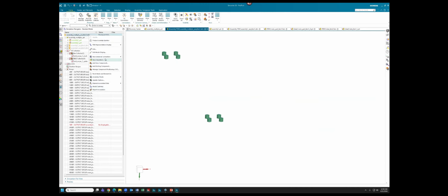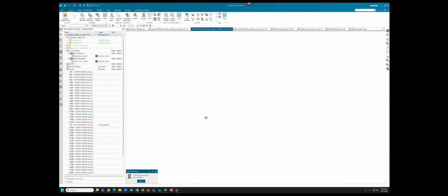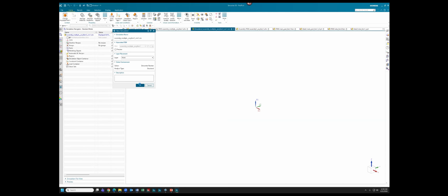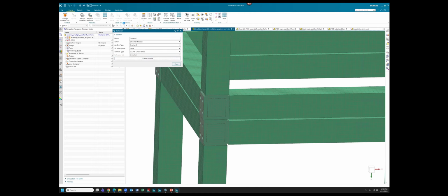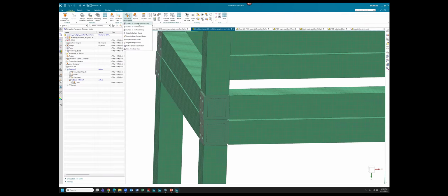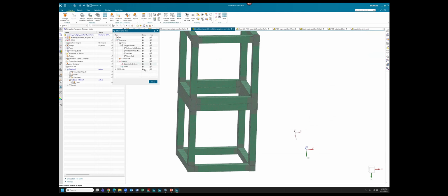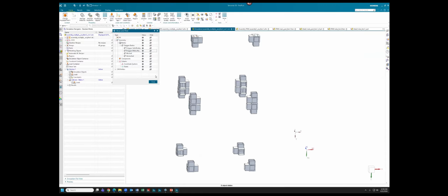Now let's talk a little bit about creating some connections within our simulation file. So the main types of connections that you create within your simulation file are within our simulation objects. So for example, if we expand these, you have a few different options here. Most relevant are glue or contact types of definitions. So for today, I was just going to briefly talk about setting up our glued connections and how you can leverage those for large assemblies like this.